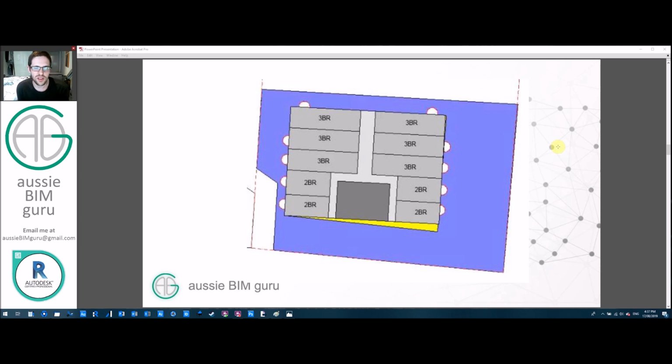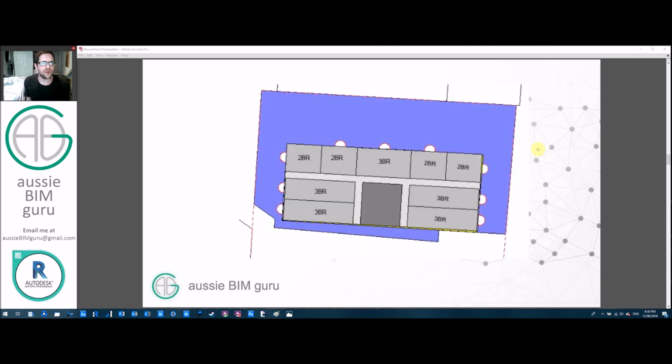So what I've done is some really generic apartment layouts, and instead of having sensors across the entire building, I've removed all the sensors except for the ones in the likely living room areas in a potential apartment layout. Now I know this isn't a very pretty layout, it's not architecturally considered, it's just a really generic knock-up, but what's important is the sensors are all placed at the location of living rooms, because in our last study we noticed that the south face of our building got no sun at any time of day in winter. Likewise, we also have our other option, our half site, which I've also set up some locations for too. So we'll look at the results of that at the end of our study and see if our designs actually comply.